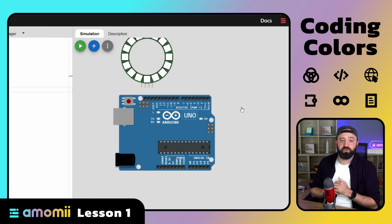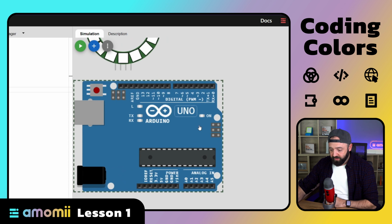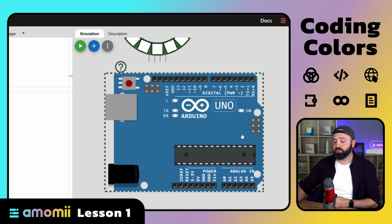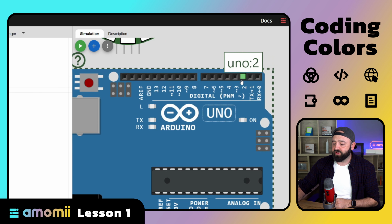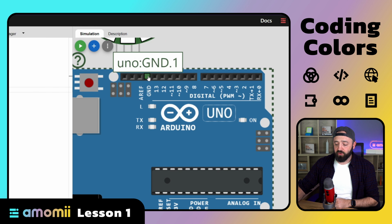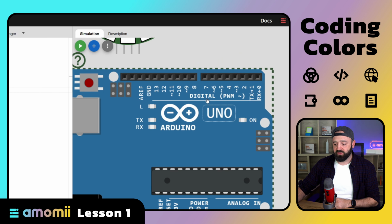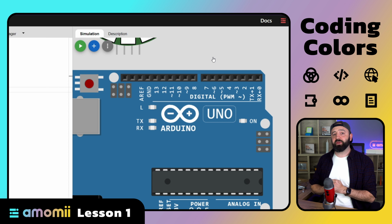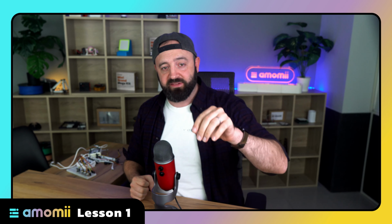Before we start connecting the wires, we'll take a quick look at the microcontroller. If we zoom in here, we can see the various parts of the Arduino Uno. We're not going to go through all of them. We'll just talk about the parts that we care about for this particular project. Across the top here, we've got different pins, which are the I/O pins, which stands for input and output. These pins can be used for sending or receiving digital signals. For example, you could connect buttons or sensors and send information from these sensors to the microcontroller, or you can send information out from these pins to output devices like buzzers, or in our case, LEDs.